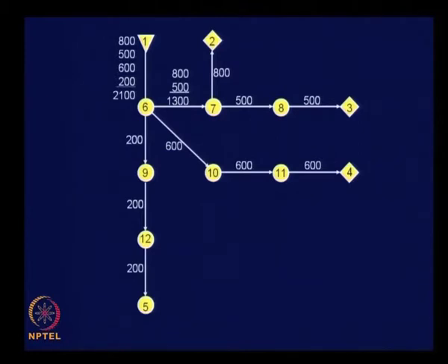So this is how we assign traffic as per the all or nothing assignment technique. We have assigned all the traffic along the shortest path, that is why the minimum path tree is used. We assign nothing to the other alternative paths to reach these nodes from 1. That is how we name this technique the all or nothing assignment technique.